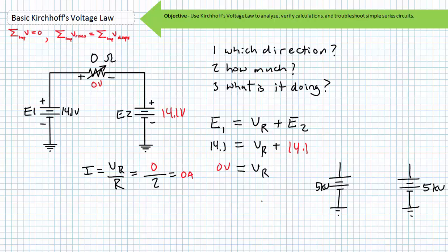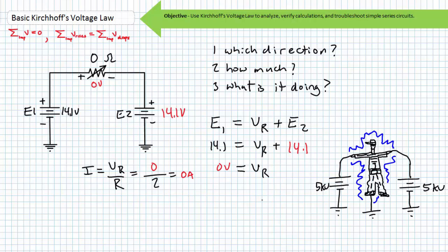This is a great time to highlight some of the really crazy properties about voltage differentials. Not that I'm recommending you verify this, but if you were to place a conductor, let's say your lab partner, across the terminals of 2 devices, each independently at incredibly high voltage with reference to ground, but equal and identical to each other, there would be no potential difference across this conductor, provided no other part of their body touched anything connected to the ground reference. If, however, a part of their body touched the ground, it would be an extremely shocking experience.